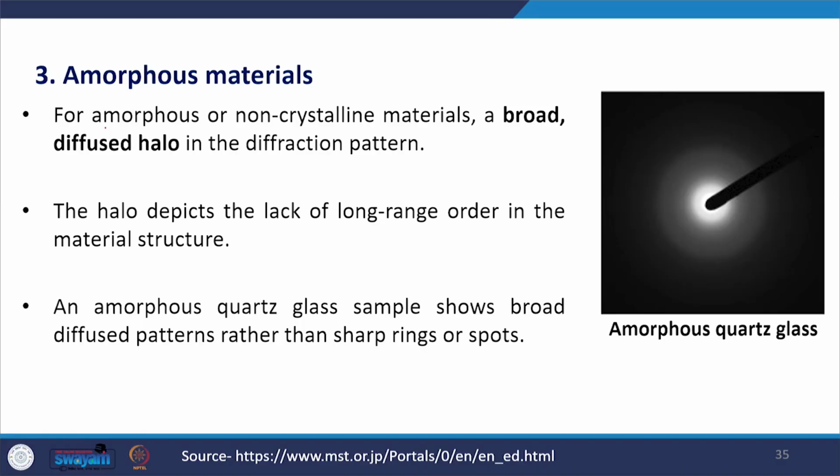The next example is amorphous material. For amorphous or non-crystalline materials, a broad diffused halo in the diffraction pattern will be obtained. The halo depicts the lack of long range order in the material structure. From this picture, you can understand this is the amorphous quartz glass. You can see the diffused ring pattern.